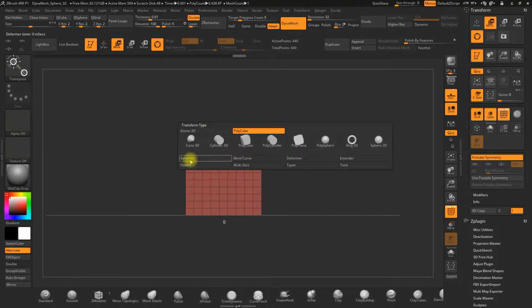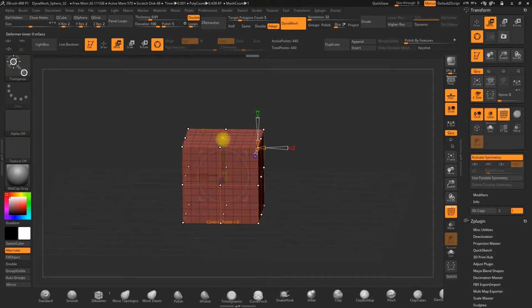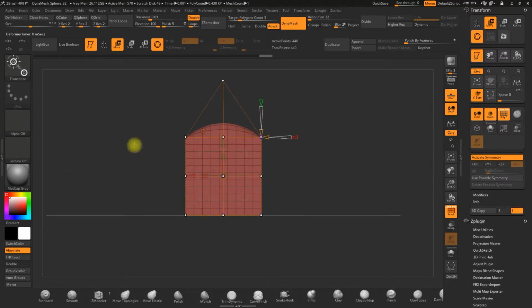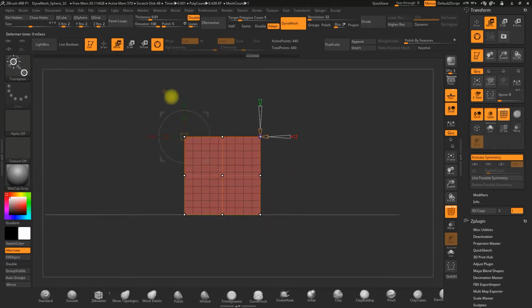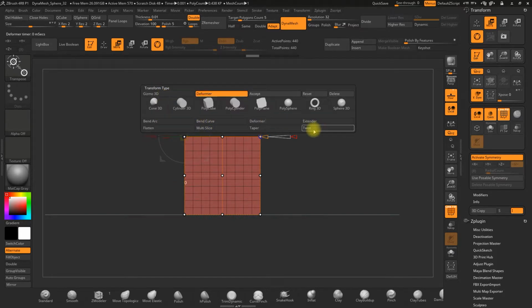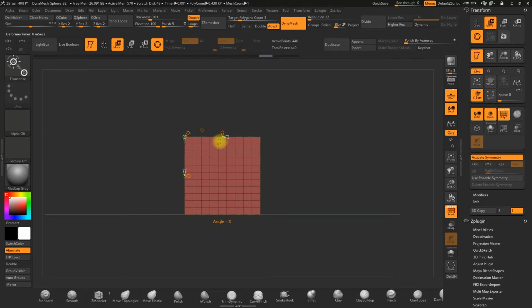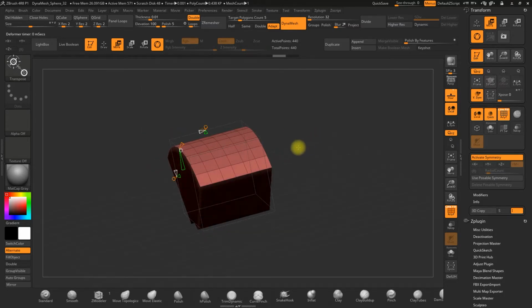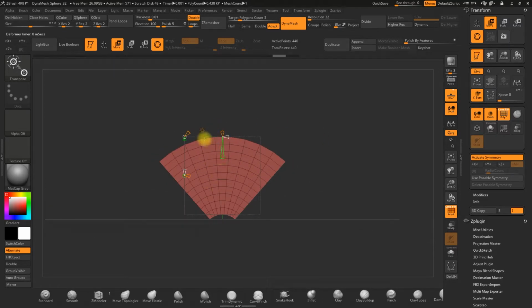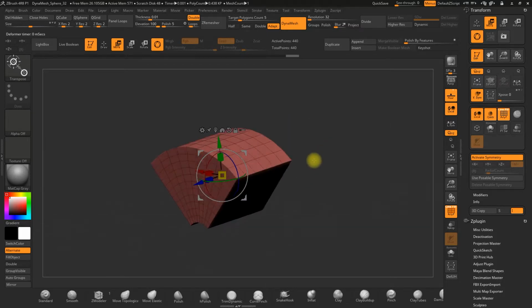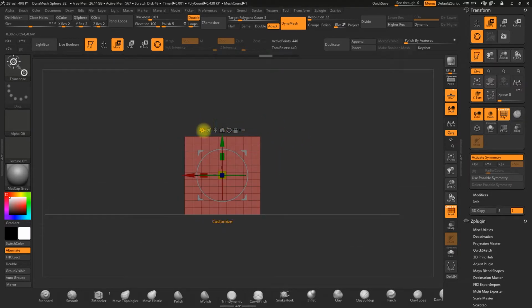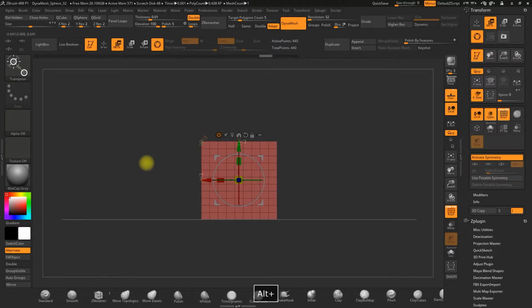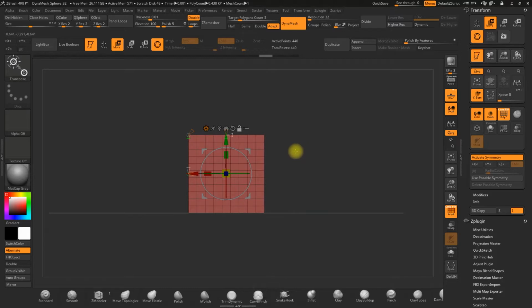If you click on this icon, you can add a deformer to the object, like this one here. This is the typical deformer that you find in traditional 3D programs, where you can modify the mesh with the points. There are other deformers, like this one here, which transforms the cube into an arch. When the shape is defined, you can click on Accept, and that's our shape set. So, these features are going to make your work easier, more precise.